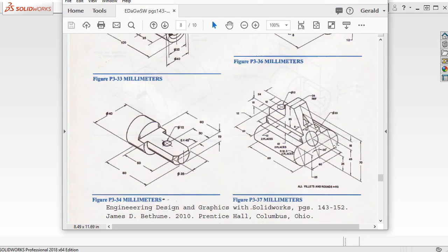And then we'll come over to 37. So 37 has the notation on this triangle that based on the depth of the cut, it will either terminate at this face. There is no call out telling you how deep it goes, so it either terminates at this face or it goes all the way through. Either way, the triangular shape really needs to be necessary because that's going to have to be a wire EDM, and if it's a blind, then it's going to have to be a sinker EDM to generate that shape. So we really need to think about what the function of that triangle is, and if it's going to be worthwhile to include in the manufacturing process, or can we come up with a better clearance or better way of alignment.